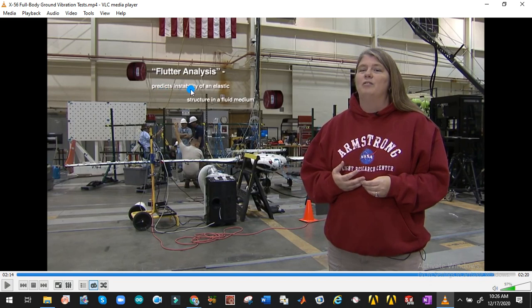What is fluttering? Fluttering analysis predicts instability of an elastic structure in a fluid medium. So it will determine the point where your structure will be in the phenomenon of instability. Fluttering phenomena can be predicted experimentally as well. What are the possible excitation frequencies where the system will be excited? We make our structure in such a way that if the excitation force of the air or medium is in this domain, then our structure should not operate within this domain. This helps us understand and avoid very expensive disasters.